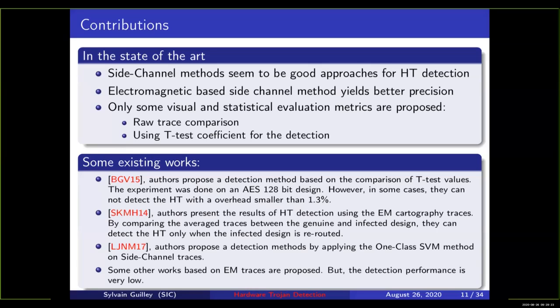In this work, we used the analyzer from SecureIC, but the only requirement for the experiments is to be able to observe the electromagnetic emanation from the chip, and that will be the traces we need to make the binary classification: genuine versus Trojan.